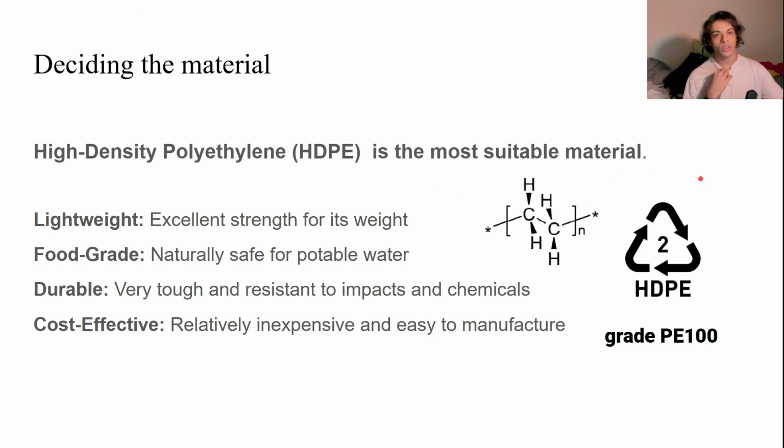The material that we have chosen here is a very famous one, high density polyethylene, HDPE, specifically grade 100, PE 100. This material has excellent strength for its weight, is naturally safe for potable water, is very tough and resistant to impacts and chemicals, and it's relatively inexpensive. So it's quite cheap to manufacture.